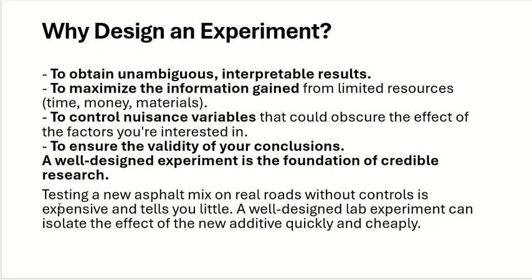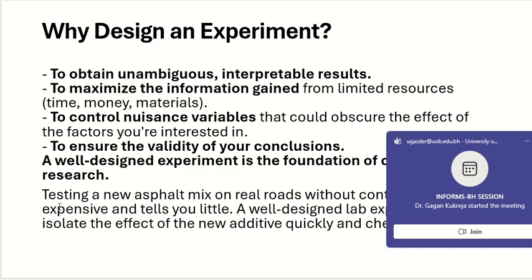If you have seen the lab experiment for asphalt, the one where we do the passing of the wheel on it, it's a standard wheel that passes a few times. Still, it's in the lab. It does not account for temperature variation. It does not account for settling of the soil. It happens, right? Settling of the soil, moisture. Moisture coming from the ground and moisture coming from the atmosphere. We have humidity, high humidity, right? So the lab experiment will not account for any of these things.